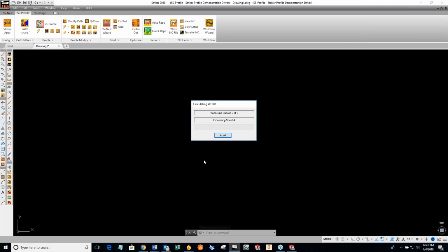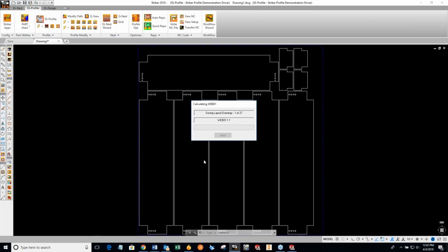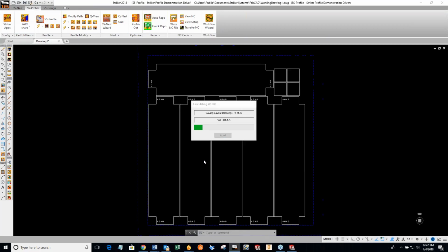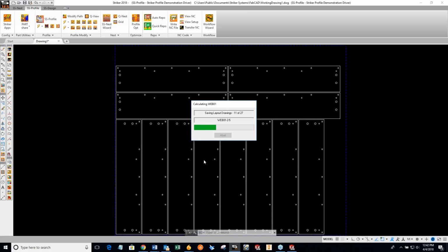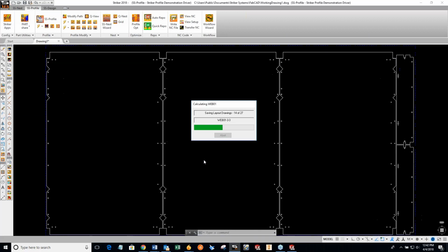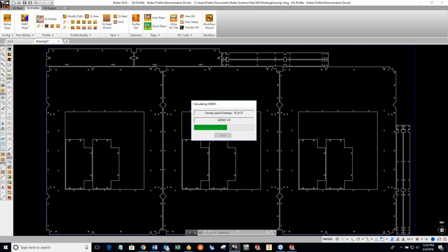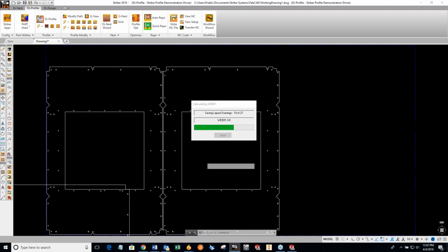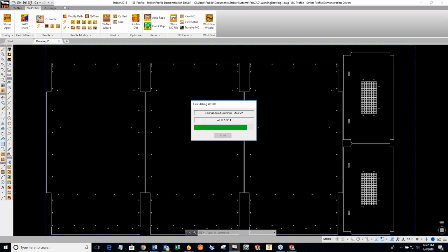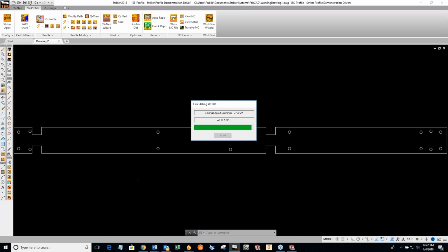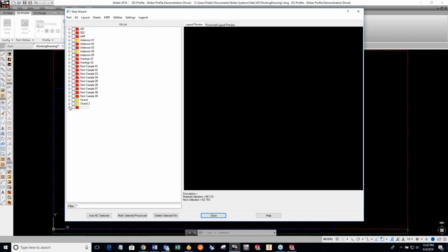Now there were 3 different material thicknesses here, the same material type, but 3 different material thicknesses, and it will automatically sort based on material type, material thickness, and also whatever machine it's going to. Now, one thing that I had turned on that I shouldn't have gone so fast and should have pointed out: when our Stryker Systems Nest software runs, I have the option of either just assigning a standard sheet size, or in this case, I told it that I wanted it to review my available sheet inventory and select the sheet size or sizes that were going to give me the optimum material utilization.